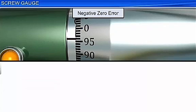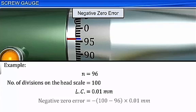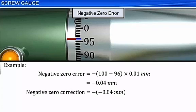For example, if the 96th division of the head scale coincides with the index line of the pitch scale, the total number of divisions on the head scale is 100 and the least count of the screw gauge is 0.01 millimeter, then the negative zero error is equal to minus of (100 minus 96) into 0.01 millimeter, which is equal to minus 0.04 millimeter. Then the negative zero correction is equal to minus of minus 0.04 millimeter, which is equal to 0.04 millimeter.